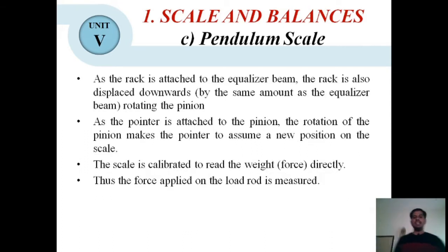As the rack is attached to the equalizer beam, the rack is also displaced downwards by the same amount as the equalizer beam, rotating the pinion. So the amount of rotation of the pinion is equal to the amount of displacement of your rack.